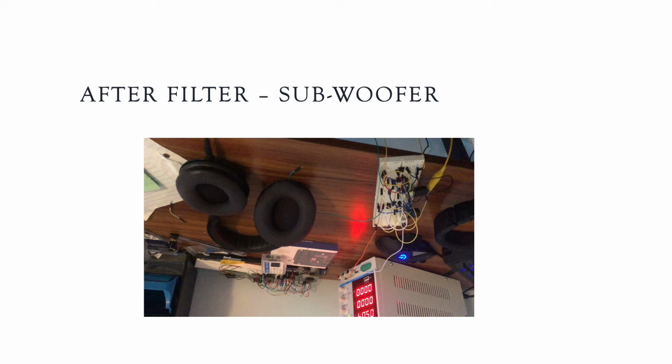You might notice that the audio is not only louder than in the previous slide, but that you also can hear the vocals more loudly than the bass line. This is because the bass line was being filtered out by the high pass filter, while the vocals were able to pass through the filter and experience the amplification of the op amp.